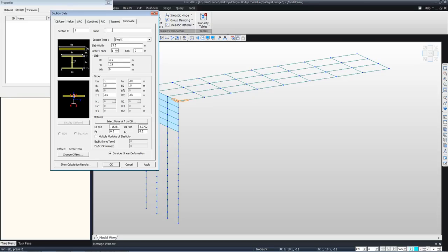Name of this girder, so I'll just name it as mid span, because I will use two different types of sections for the main girders, because I want a non-prismatic or tapered section between my abutment and up to 15% of the span. So I'll just use separate sections for mid span and a separate, tapered section for the abutments.